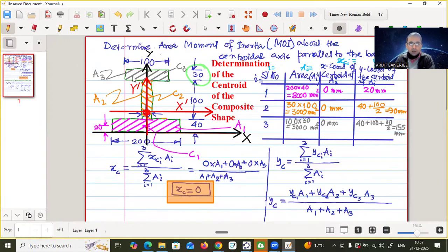That means, if we want to determine the moment of inertia of the complete object, then if we can calculate the individual moments of inertia about some axis, we just add them and we will get the moment of inertia of the complete object. First of all, this should be clear. We can break the object down into regular shapes, determine the moment of inertia of each, and then simply add them.